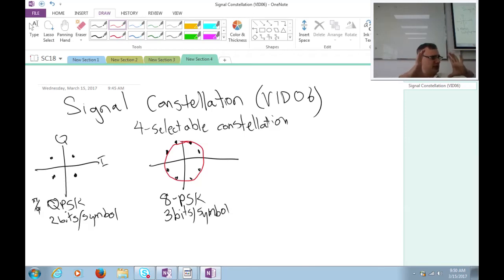It can clip and kind of smoosh in those corner points, and that makes it very difficult to detect, especially since you never get a QAM constellation arriving perfectly intact. It's always rotated some random number of radians in phase when it gets to your receiver, so you're not exactly sure, at least first off, where to draw your decision points. So there's a lot of benefit.